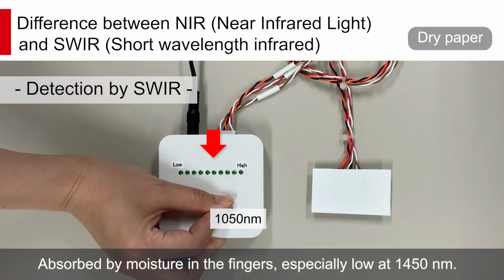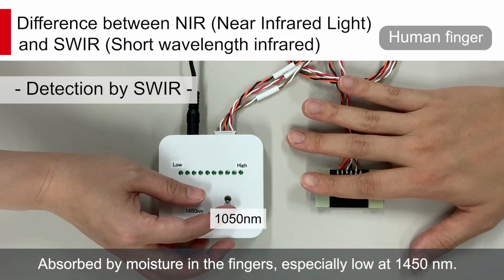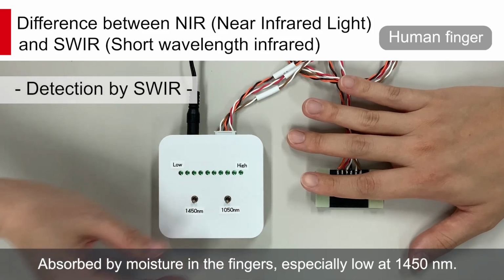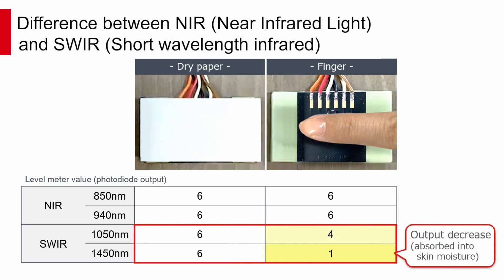In SWIR, there is a difference in the value detected because it is absorbed by the moisture in the skin. NIR can also determine the presence or absence of an object, but the value is the same for both paper and human fingers. With SWIR, it becomes possible to detect differences between human skin and inorganic objects.